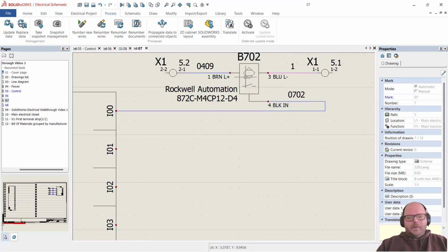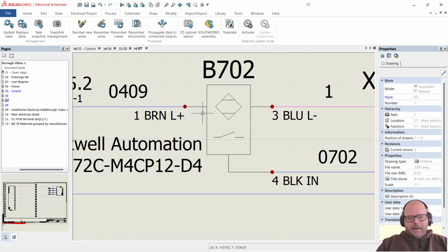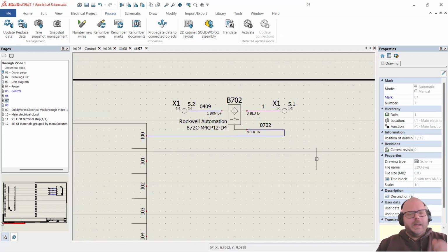A lot of times the proc symbol will be this switch inside this diamond, and then we just come out each side of the diamond. And so that symbol gets a lot smaller when we think about it. So there's a lot of things we can do, but the text really shouldn't be the concern. The fact that there's a lot of it and it's crowded, because that's information. It's information that's only going to help somebody build this thing. Like, imagine I hand this sheet set to a maintenance person that has never done electrical work before. He needs as much information as I can possibly give him.